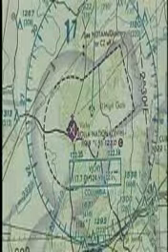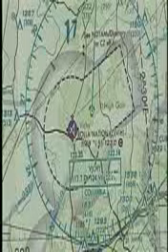In order for you to conduct VFR operations within the lateral boundaries of Class B, C, D, and E airspace, you must have a ceiling of at least 1,000 feet. In addition, VFR pilots cannot land, take off, or enter the traffic pattern unless the visibility is 3 statute miles or better. These requirements give VFR and IFR pilots the necessary visibility to see and avoid each other during approaches and departures.